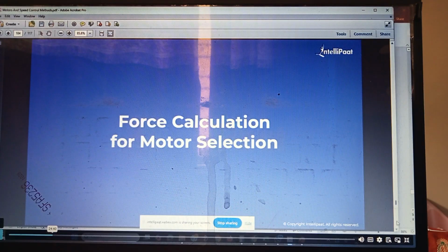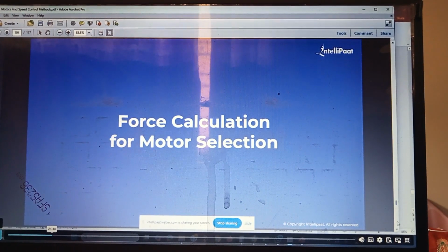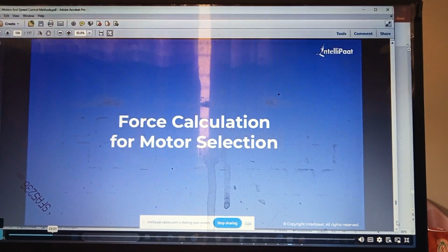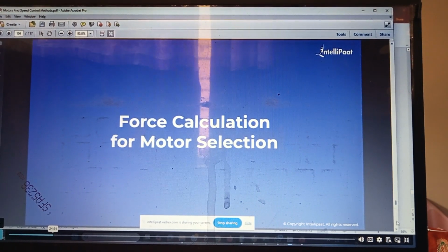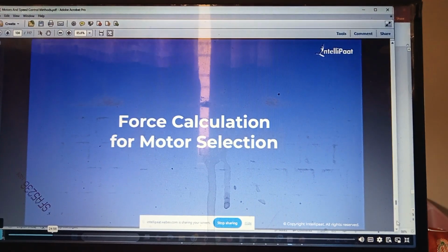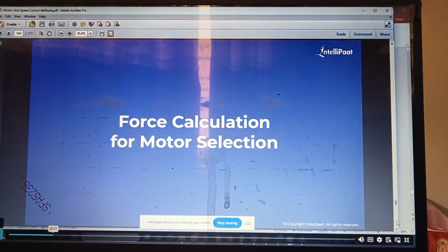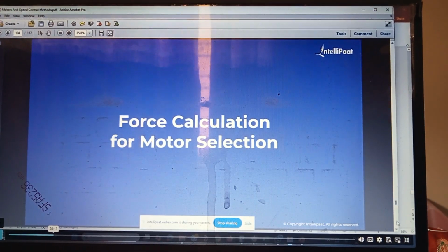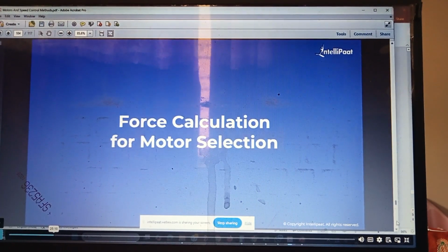Alright, so with this, we now come to a conclusion that in general, PMSM is the best choice for high-end vehicles. BLDC is generally good for low power applications, typically less than 1 kilowatt, less than 2 kilowatt, that kind of applications. BLDC in general is a cheaper solution, but their problem is that they have more torque ripple. More torque ripple means a jerk kind of feeling, not very smooth operation, right? So the cost sensitive segments prefer BLDC, whereas the higher cost vehicles naturally go with PMSM.